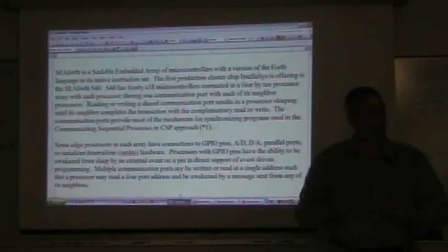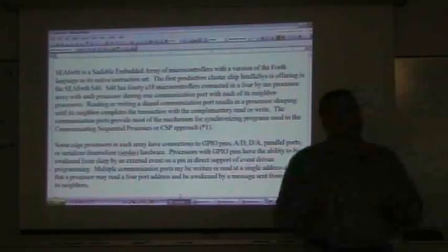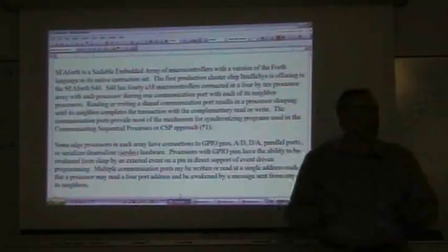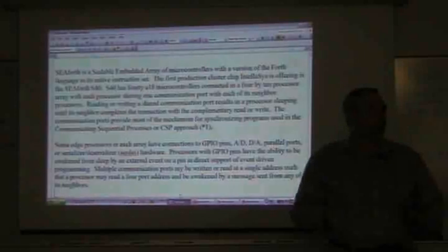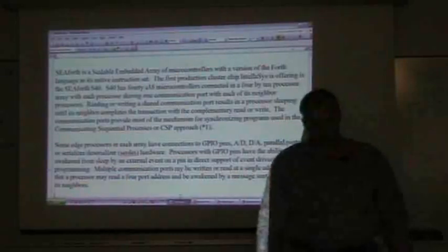And this hardware Forth is particularly compressed because these opcodes are no longer entire words. They're little 5-bit opcodes that we pack multiple opcodes into a word. So our Forth programs become even more dense than normal Forth programs, and they become faster than normal Forth programs because we're executing our primitives at the hardware level.